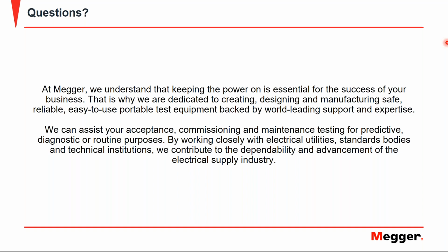Now, with VLF and tan delta testing, they're going to give you an evaluation of the quality of the cable, but the one thing that they lack is they're not going to give you a localized evaluation of the cable. So with partial discharge testing, we're able to localize the bad spots within the insulation of the cable to isolate it down to where the partial discharge is coming from.